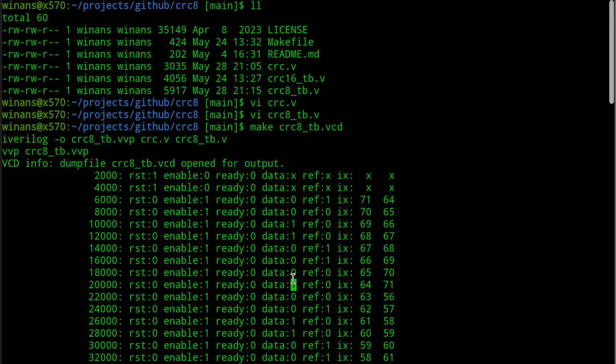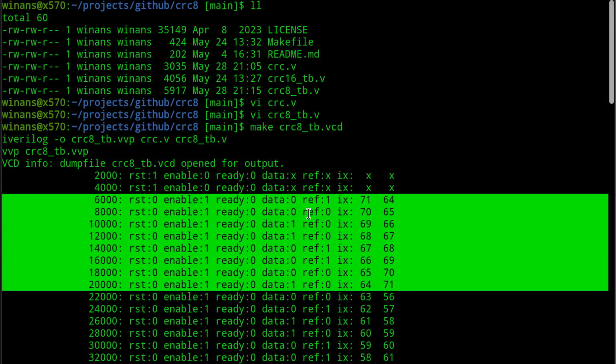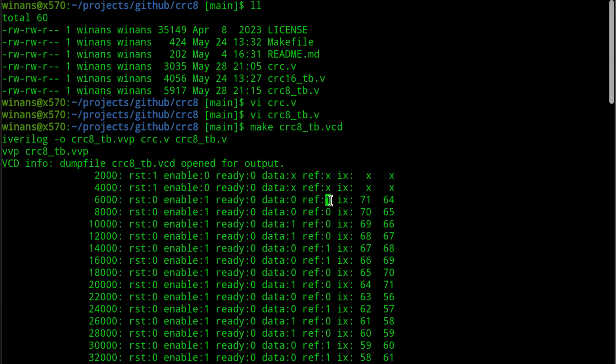right? This is the first 8 bits. You can see the 31 here, and you can see the backwards 31 there. This is going to go 71 down to 64, and then move to the next one at 63 and keep going. The reversed one, the reflected one, is going to go from 64 to 71, which is why this bit here is the value you see up there and so on. Okay? So this is reflecting. It's just simply sending the bits out in the opposite order on a byte basis into our CRC generator.